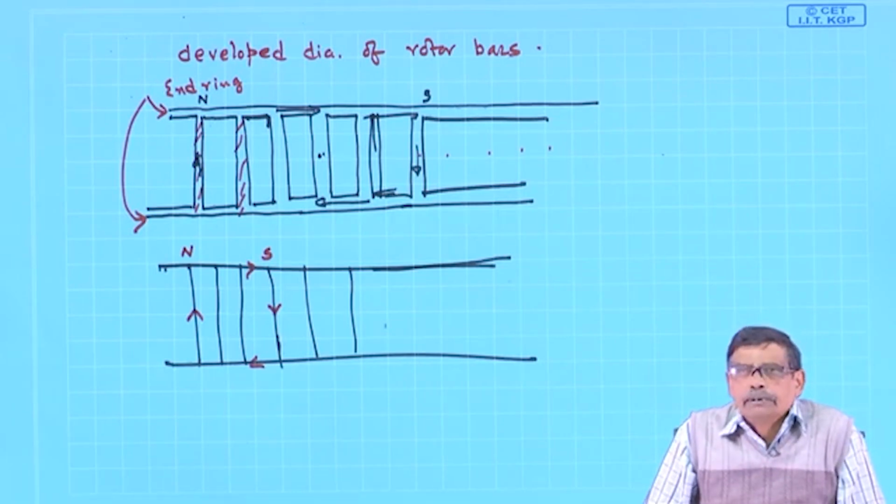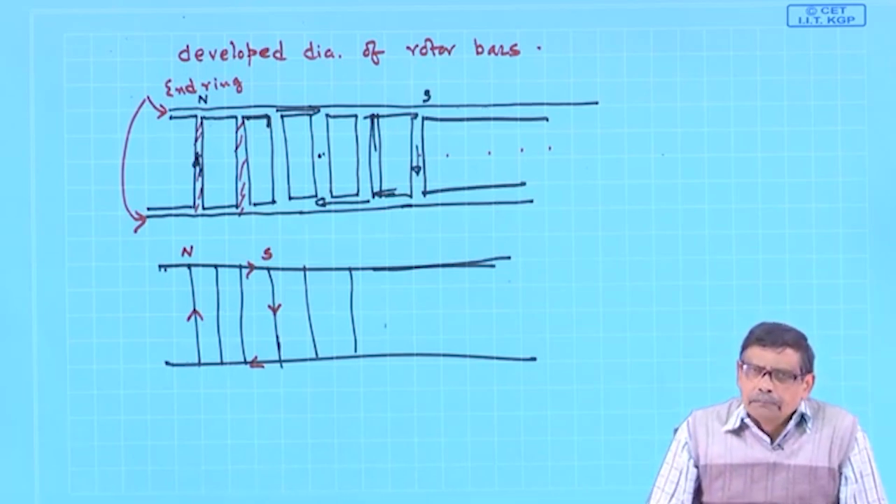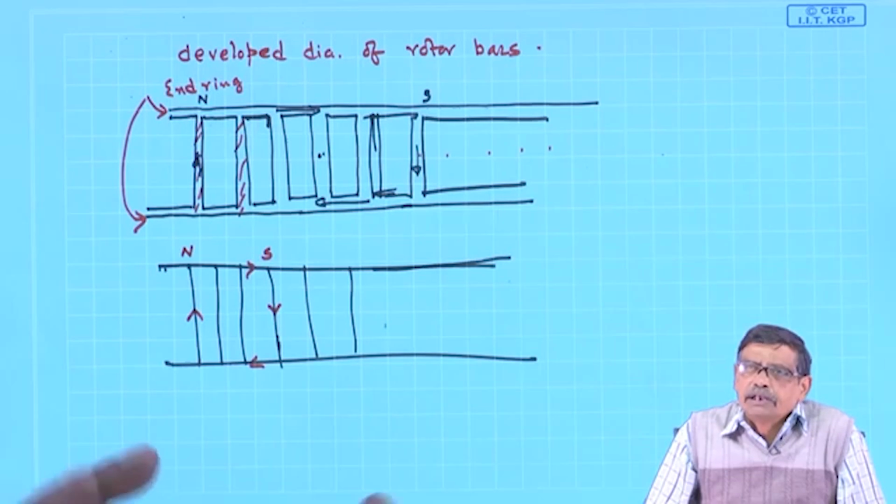You can have 2 separate stator 3-phase coils, energized one at a time. Obviously, you are reducing the utilization of the machine space available for copper. Can it be possible that I use a single distributed 3-phase winding, but by reconnecting the groups in a particular fashion, get a 3-phase winding which will sometimes behave like a 2-pole?